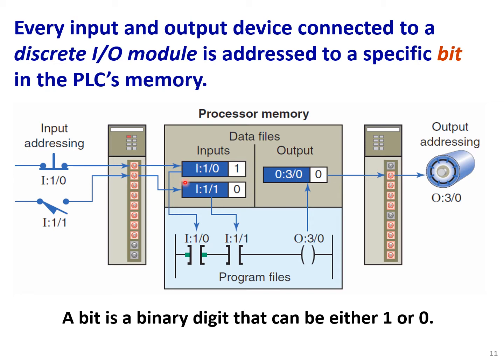And here in the memory of the PLC, we could refer to those inputs by selecting the address here. For example, the first input is I10. The value of this input for this moment is 1. It means that it's true or is closed here.